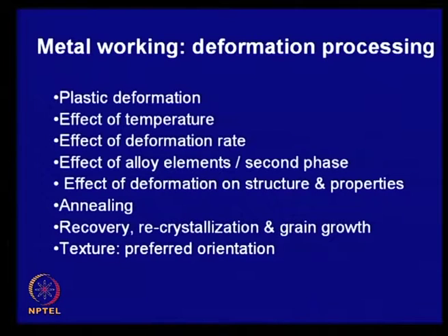We have seen in last several classes that metals and alloys, when they solidify, are made up of either one or multiple phases, and that there is segregation in the metal. Metal is known for its ductility, but cast metals have relatively poor ductility, and unless they are given working or deformation processing, we do not get the optimum amount of strength and ductility.